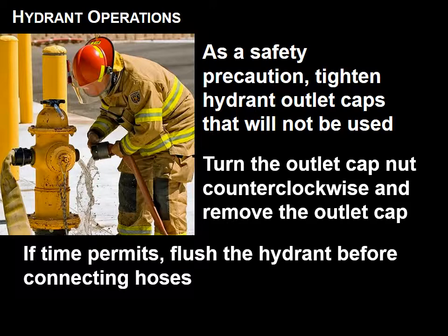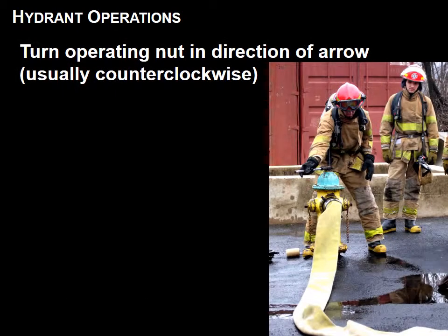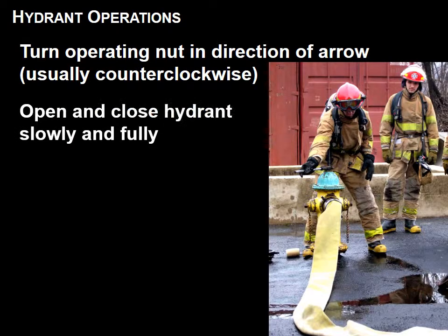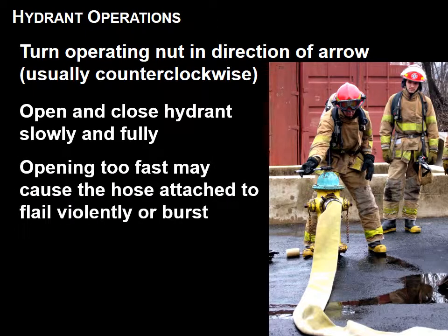I'm going to connect the hose. Stand on the opposite side of the opening discharge outlet. Turn the operating nut in the direction of the arrow, counterclockwise. Opening too fast may cause the hose attached to flail violently or burst, and closing too fast can cause a sudden increase in water pressure within the water system, causing a water hammer.